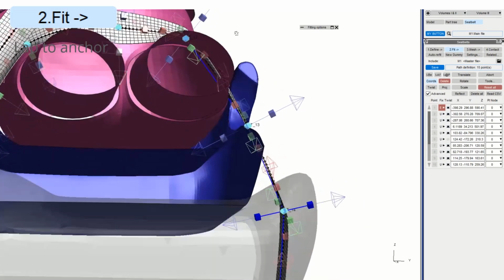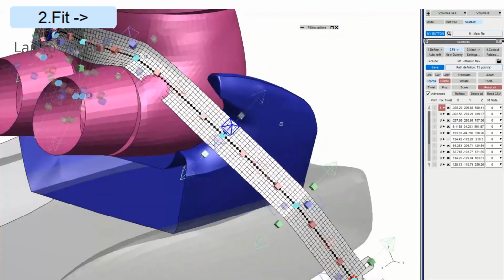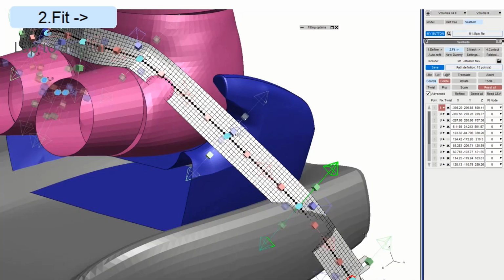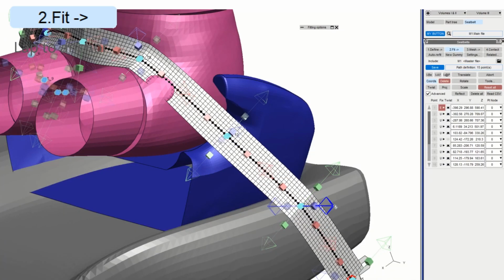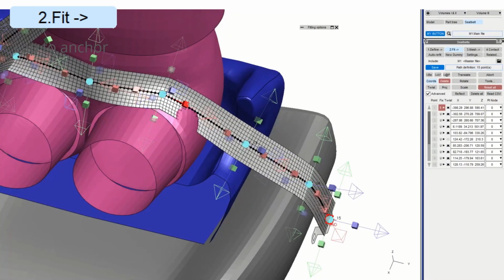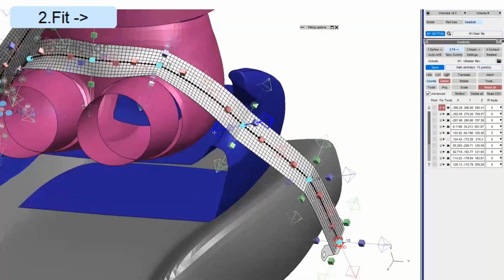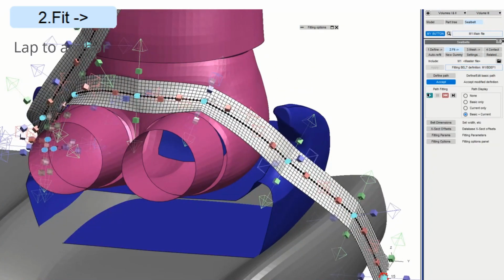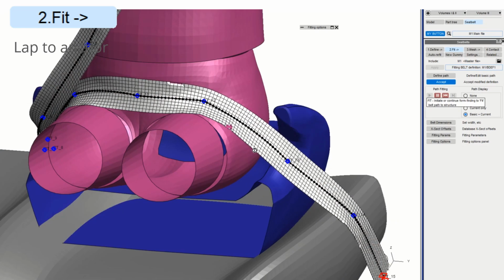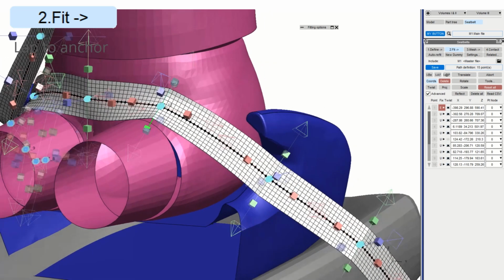We don't want too much slack in this belt system, so that 0.13 there, we don't want it with too much curvature, because that will require a lot of belt fitting iterations, and if we let the belt fitter run for a very long time, it's likely to screw up some other parts like the slip rings. So we're going to try and manually remove slack by making the belt as straight as possible.